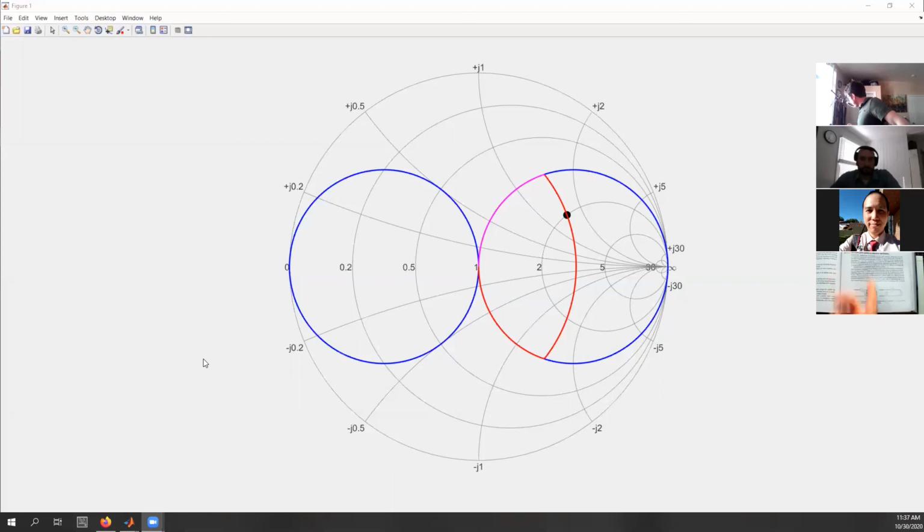That is a good point the book makes: this lumped element idea is probably best only used for lower frequency stuff, below a gigahertz. When you get higher and higher, you wouldn't use a lumped inductor anymore. You would use the little stubs. But the actual physics of what the stub matching is doing is behaving like equivalent series and parallel networks. So that's kind of cool. You can think of them as an equivalent capacitance or inductance anyway.